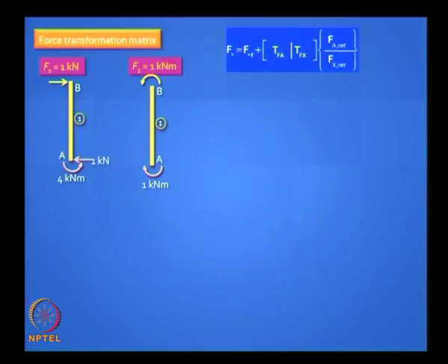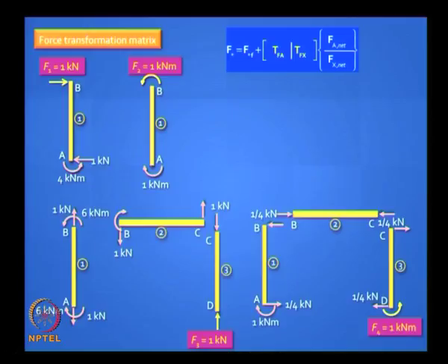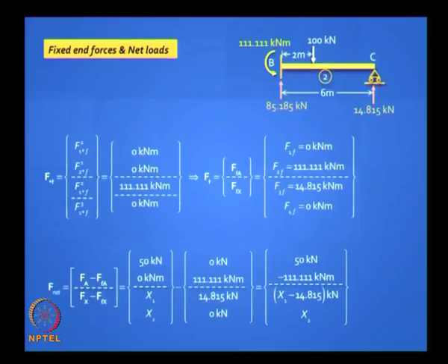Force transformation matrix, much smaller, much easier. F1 equal to 1, F2 equal to 1, same results, these two do not change. F3 equal to 1, F4 equal to 1. Same, only we've renumbered them. F6 became F3, F7 became F4. The size of your TFA matrix is shrunk to a nice compact size, right? You can interpret the results very easily. You got your TF matrix.